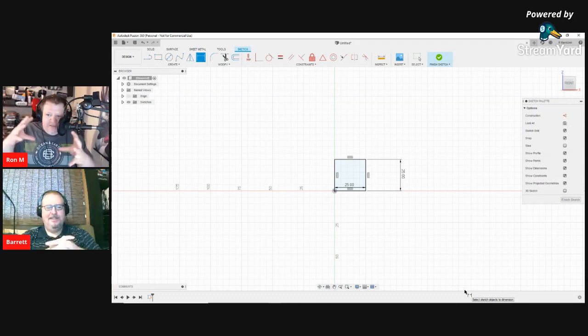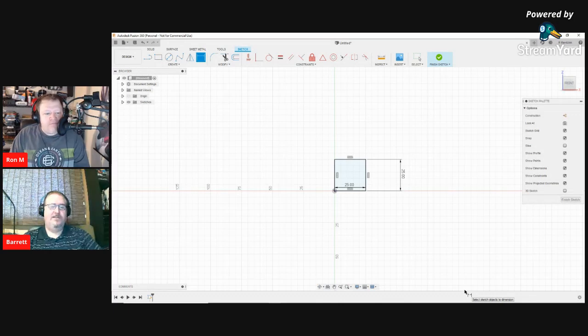So we're just locking in the size that we want to create, correct? You're locking in the size and the location. So you're registering it within space, so that it has an absolute position. You can start off and not do that early on, but it's bad practice and it will eventually bite you. So while it's really easy and you're working with simple objects, I suggest getting used to the practice, because as things get more complicated and you start making really complex shapes, not having things fully defined will bite you every time. Been there, done that, bought the t-shirt.